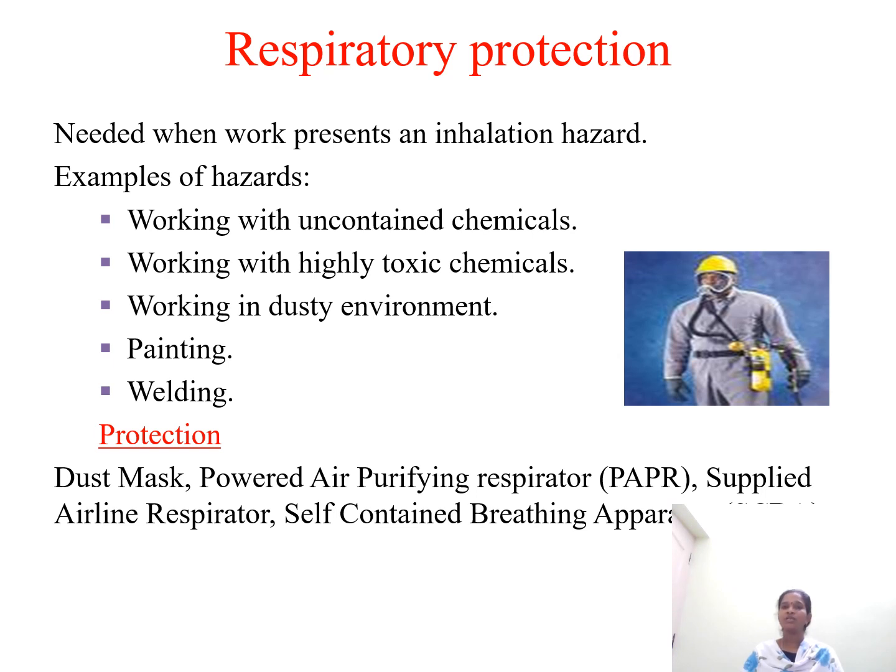The protective equipment includes dust mask, powered air purifying respirator, supplied air line respirator, self-contained breathing apparatus. These respirators will be used when engineering controls are not feasible or not being implemented. And when exposure levels exceed the permissible exposure limit, a respirator will be suggested.